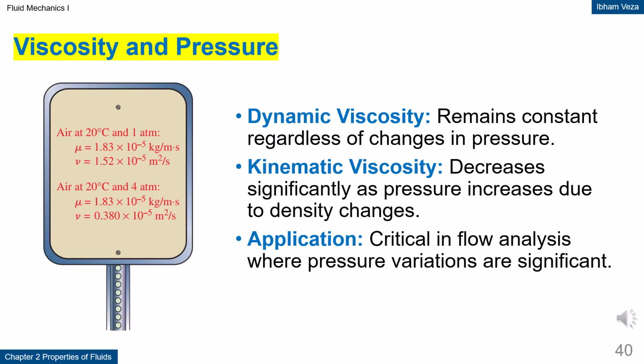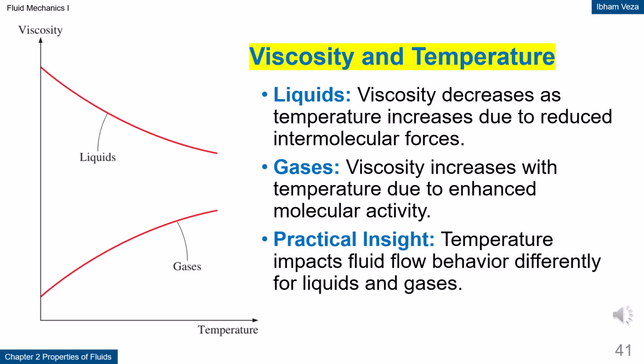Viscosity and pressure. Dynamic viscosity is relatively insensitive to pressure. In contrast, kinematic viscosity can change significantly because it depends on density. When pressure increases, fluid density also increases. This causes changes in kinematic viscosity. This concept is important in the analysis of high-pressure flows.